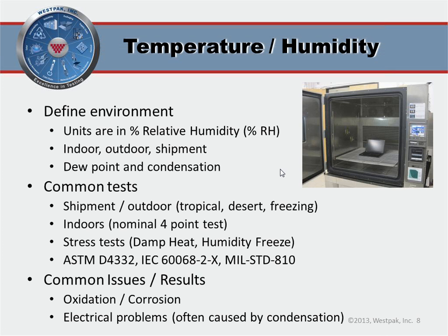But sometimes people will test a 4 corners profile, which is low temperature, high and low humidity, so maybe 5 degrees C at 15 and 85% relative humidity, and then elevated temperature, high and low humidity, maybe 35 degrees C at 15 and 85% relative humidity. Again, these conditions will vary a little bit industry to industry.